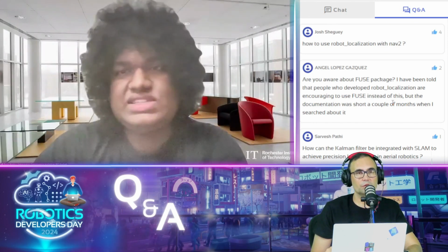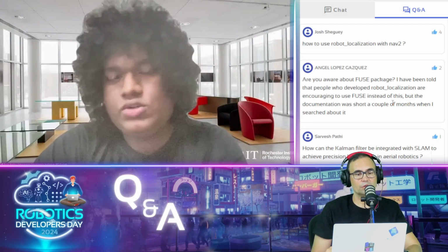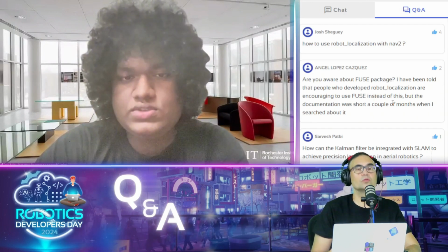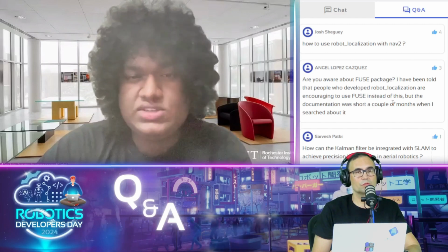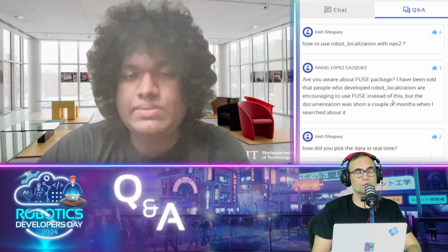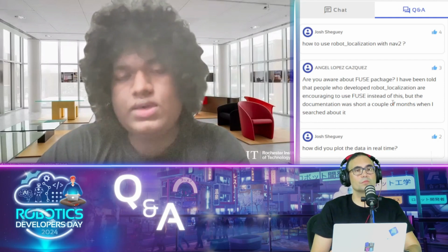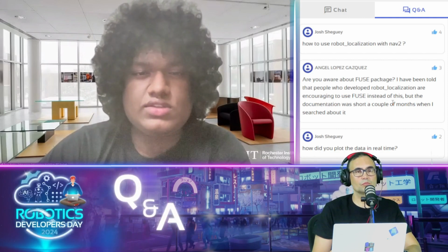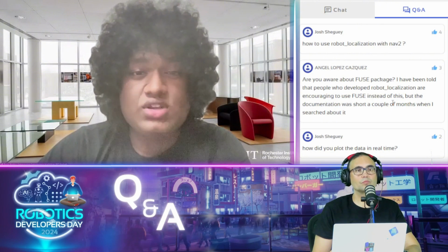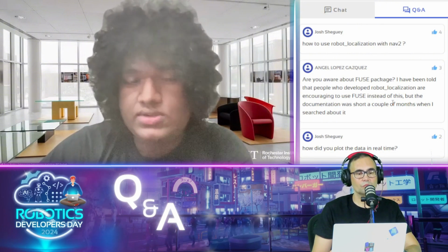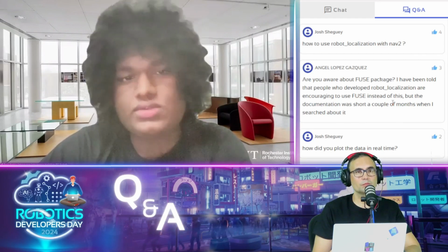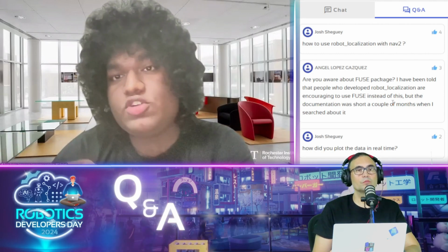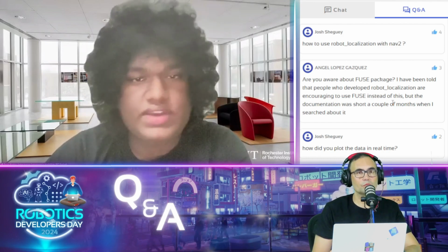Yeah, so as I was saying during the setup, there's no limit on how many sensors or what types of sensors you can put in. The limit is on the 4 types of message definitions that you can put in, like odom, pose, IMU, and so on. As long as your sensor can comply with the REP 105 standards, then your sensor will work. So visual odometry, laser scan matching, GPS, that will all combine together just fine.